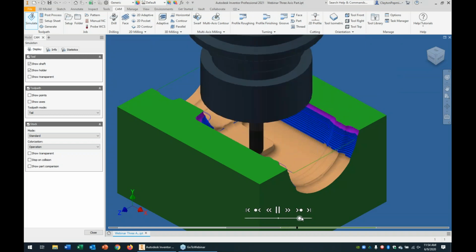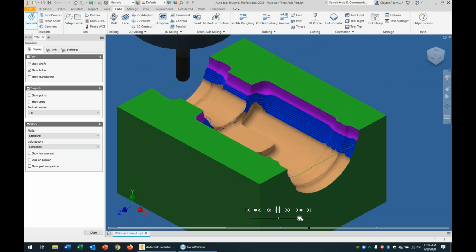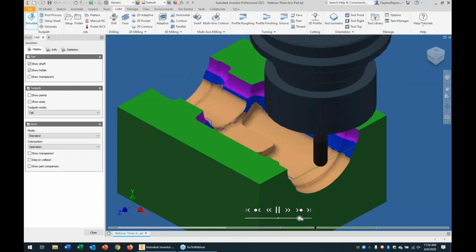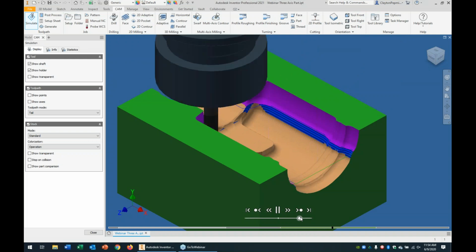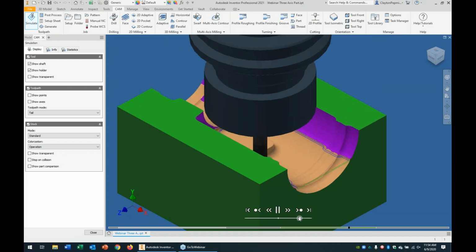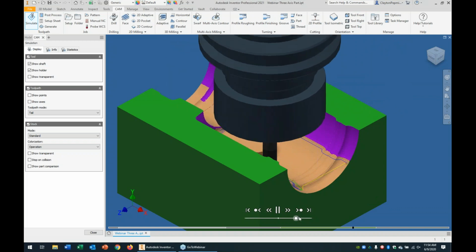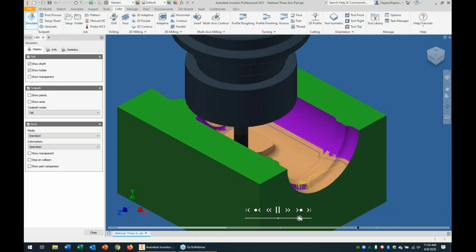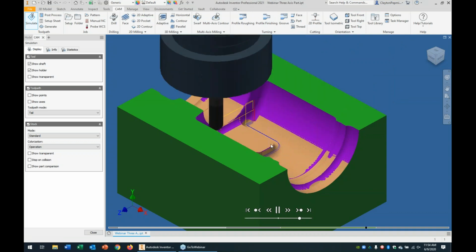I've got a fairly fine step down because when you're machining in real life, you use fine step downs to get smoother finishes. As a pattern maker, I had to polish a lot of my work, so the more I could do with the tool, the less sanding I had to do when it got to the polishing bench. So I am used to fairly small step downs. But notice, even though I told it to stop at 45 degrees, it's still going to go deeper because even these grooves and stuff have vertical sidewalls.